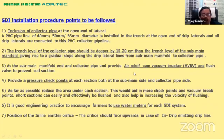And here, mind you, the drip lines are not visible, since they are going underneath. Therefore, we need to have appropriate pressure checking points both at the submain and the collector level. It's very simple. You just take a tube out, bend it, and then you can have a portable pressure gauge and check the pressures. So pressure check points are very important. And also, when we design the system, as far as possible, try to keep shorter sections so that we will have efficient flushing and the water will keep getting circulated.